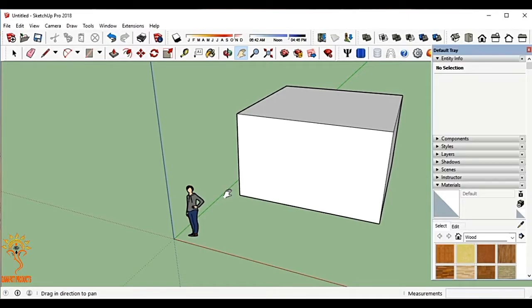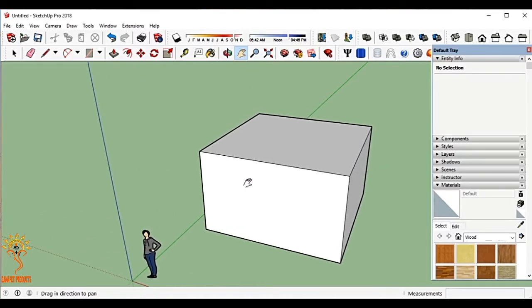And as we discussed for the azimuth angle, we will face the PV arrays to the south if we are in the northern part of the world, and similarly we will face them to the north if we are in the southern part of the world.